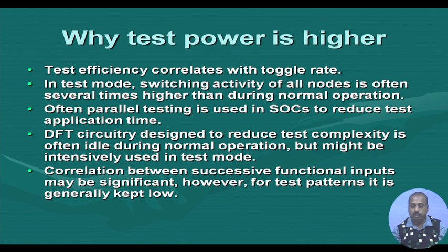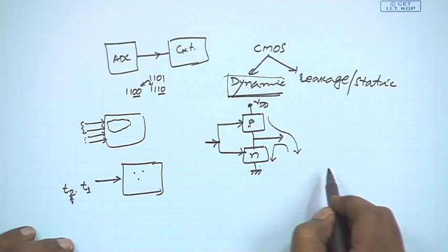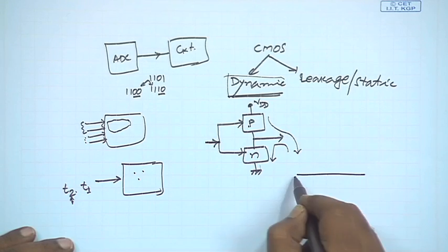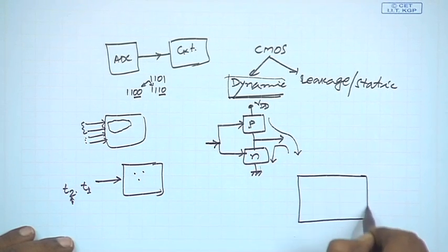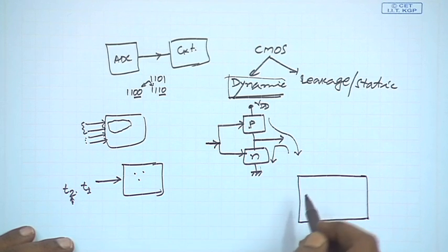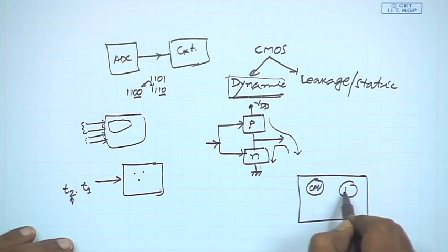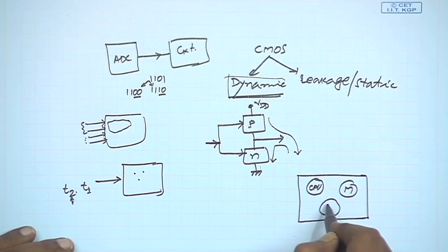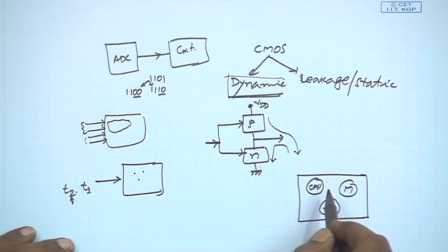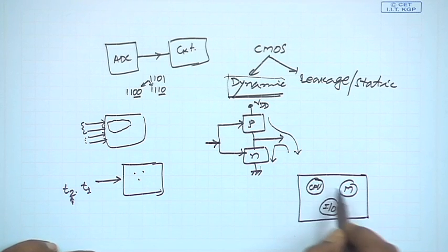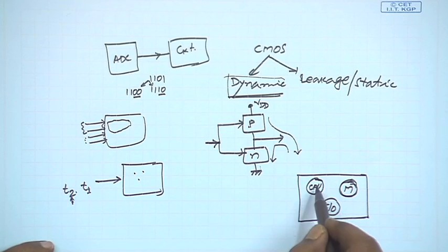What we mean is that in a system on chip design, if this is your chip that you are manufacturing, then in this chip we have got different modules from different vendors. Maybe we have got a CPU core from some vendor, a memory core from some vendor, then one IO core from some other vendor. These are the different modules that we have. Now, since these modules are not designed by me, I do not know their details. So I cannot generate test patterns for them.